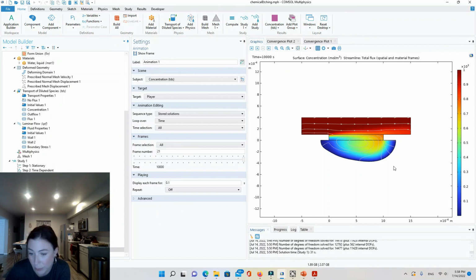And the other thing to keep in mind is that because it's an exothermic reaction, you have increased temperature in the bath. So you can imagine, since this is a wet etch, you've got your substrate with your metal layer on top here that you're etching, and the whole bath is getting exposed to the exothermic reaction, so the whole bath is increasing in temperature, which impacts the reaction rate as it progresses.